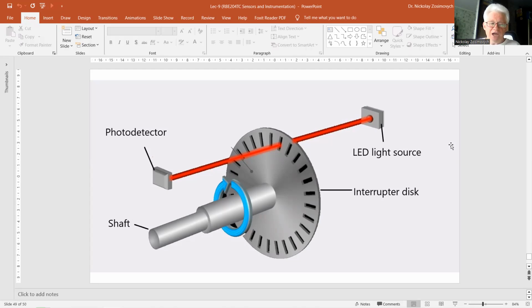And this approach allows the use of just a single detector and makes additional detectors for determining the direction of movement unnecessary. It is also easy to read codes with a non-regular format, for instance, pseudo-random code. Such codes may yield higher accuracy because they are less noise sensitive, although the scanning may slow down the system. But for many applications, such as navigation, this is not a serious limitation.